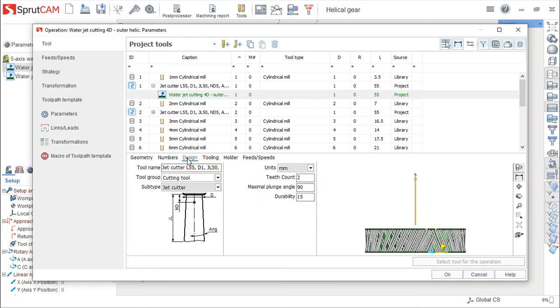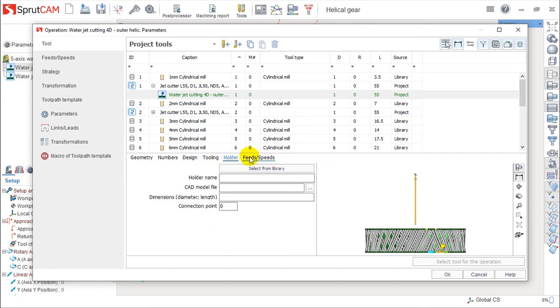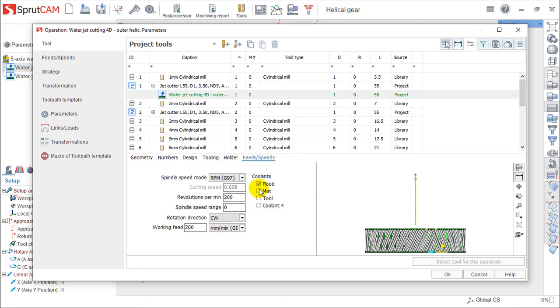Again, the position, the design, which also should be defined, but it's not crucial because if we are dealing with a water jet, we don't have actually a milling tool to replace. It's always the fluid of water mixed with some other agent that does the cutting. Neither holders can you have because you have a head on the machine, and the same for feeds and speeds, which is also not very difficult to understand.